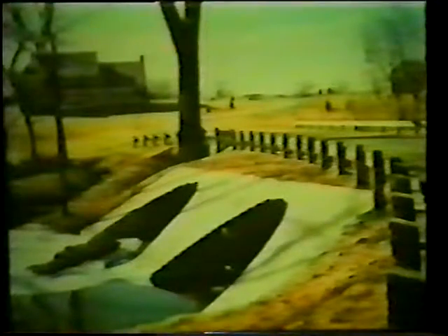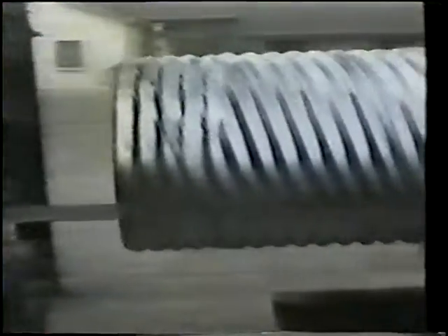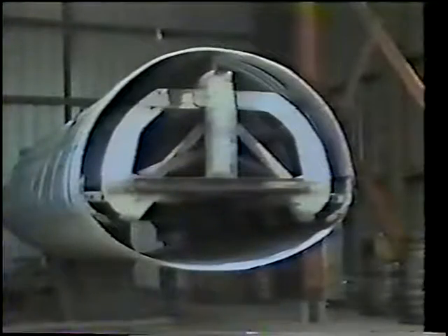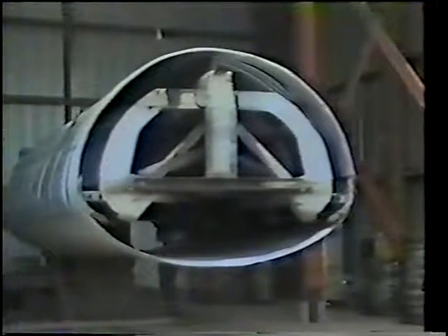Corrugated metal pipe, made of steel or aluminum, are used for gravity sewers and culverts. Galvanizing is the most common form of corrosion protection, but aluminum, asphalt, and polymer coatings are also used. Arch or elliptical shapes may be specified to meet particular site or flow conditions.